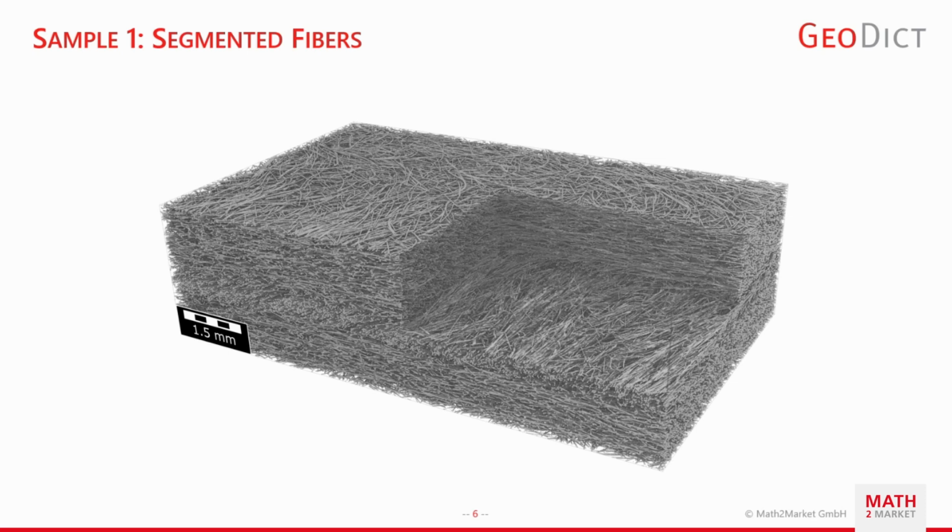So in the top layer and in the bottom layer, the fibers are oriented in the direction basically into the CT scan, into the image plane, and in the middle they are oriented out of this plane. That's the process that usually happens with injection molding because the fibers orient themselves with the flow.